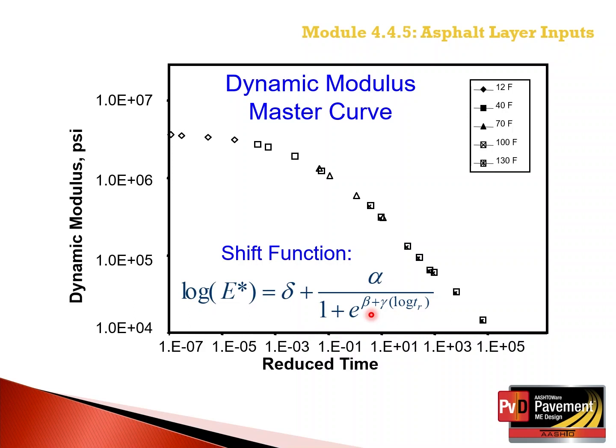Most designers and laboratory technicians typically use the actual dynamic modulus values themselves in comparing the stiffnesses between different asphalt mixtures, rather than comparing the coefficients from the master curve. The coefficients generated from the master curve exhibit less difference between significantly different mixes than the actual dynamic modulus values, because the coefficients are determined or derived over a wide range of temperatures and loading frequencies.